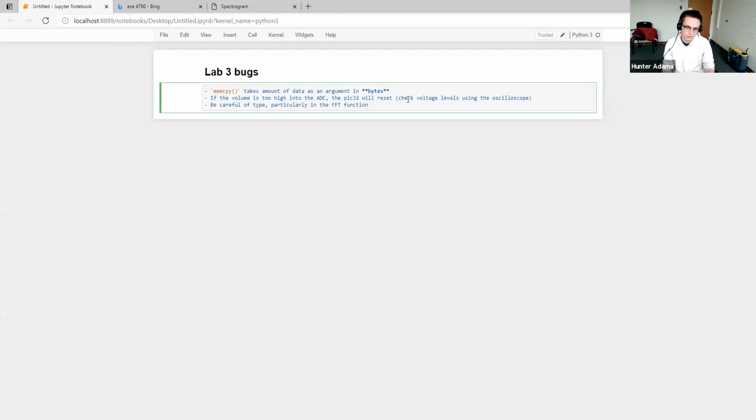Yeah, the other thing I wanted to mention, I've seen this in a few groups, is I have pointed you to two pieces of code as recommended starting places. One is the example on the DDS page that draws an FFT, and that's to see how to pass inputs and get outputs out of that FFT function. And the other piece of example code is the examples listed on the ADC page on the course website, which shows you how to set up the ADC and read it in software as opposed to DMA.